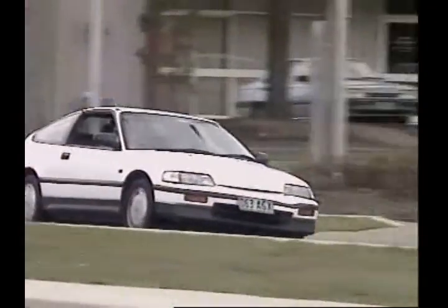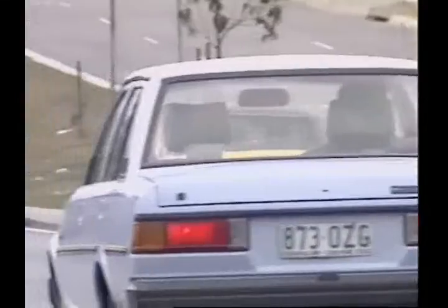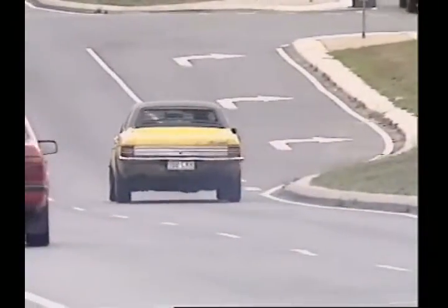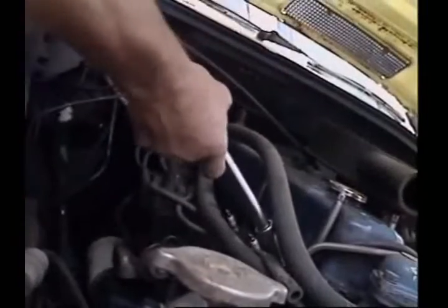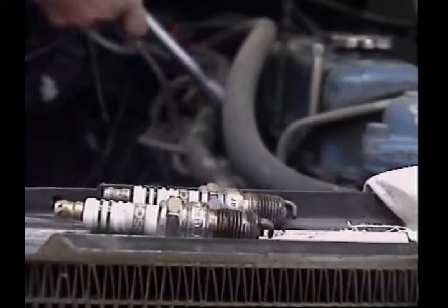A rich air-fuel mixture has less air in proportion to the amount of fuel. A slightly rich mixture can produce more power at lower temperatures, but the extra fuel it uses steps up fuel consumption and emissions. A too rich mixture fouls spark plugs and causes incomplete burning, and that reduces power.